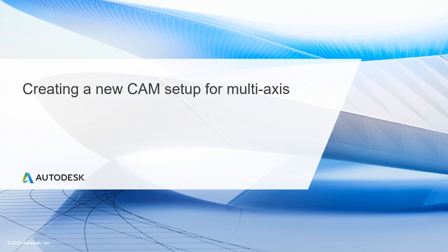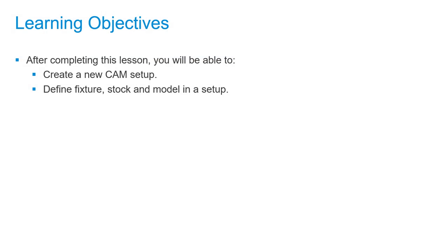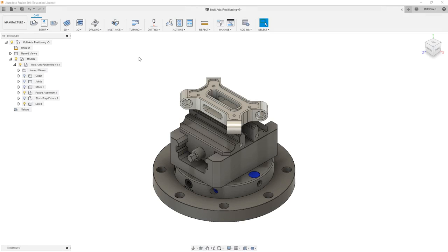In this lesson, we'll be creating a new CAM setup for multi-axis. After completing this lesson, you'll be able to create a new CAM setup and define fixture, stock, and model in a setup. Let's carry on with the file from our previous example, and let's talk about creating a new CAM setup for